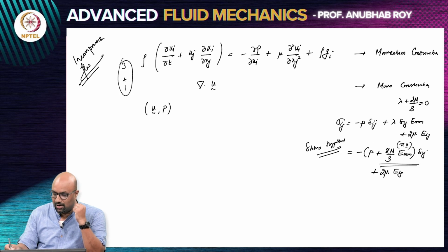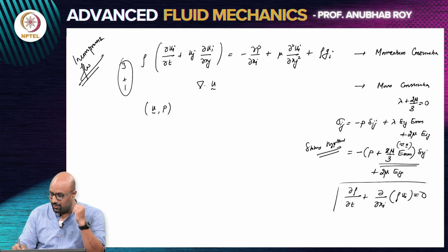So, this is all for the scenario if it is compressible. So, you can write down the corresponding modified form for the compressible equation, and in the compressible scenario you would have to then go back to your mass conservation and realize that your mass conservation equation is going to take this particular form, the equation of continuity.